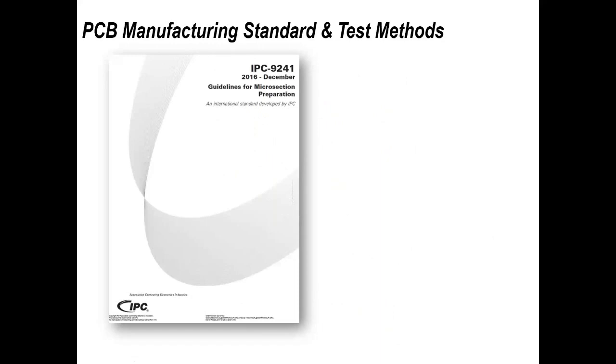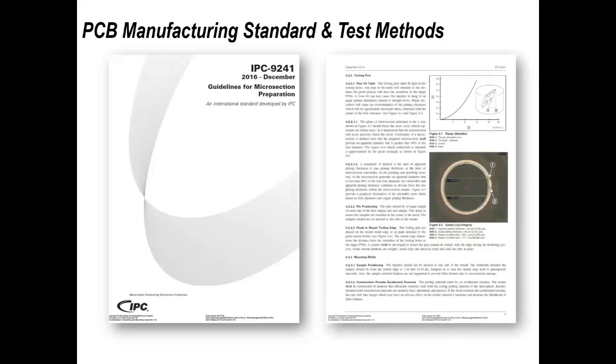Now, in addition, there is an IPC document, 9241, which is detailing the methodology for microsectioning. This includes other things other than just PCBs, but primarily it's PCB related.